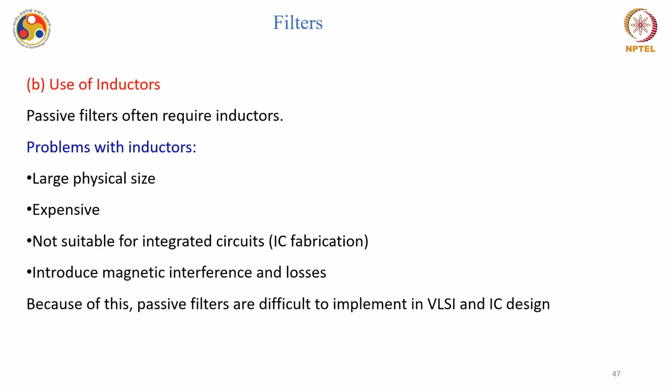Now, although the LC based filters, maybe high pass or low pass, were able to provide a sharp cutoff frequency, they have a requirement of inductors. So, all of them were having one or multiple inductors, and when you use inductors, particularly when you deal with IC and other things, it has a larger physical size because it is basically a coil.